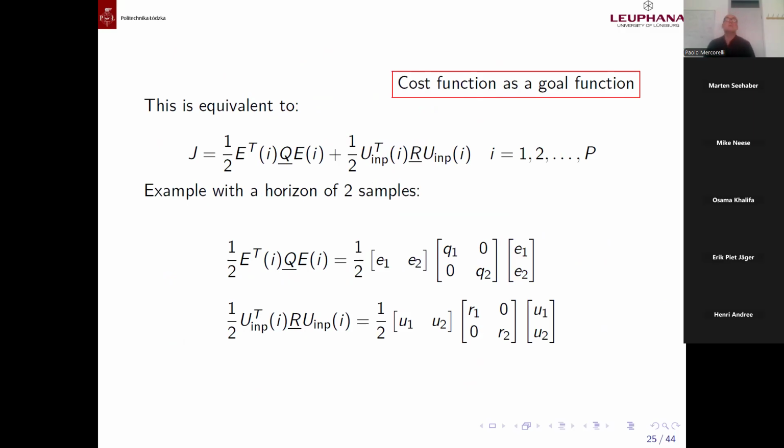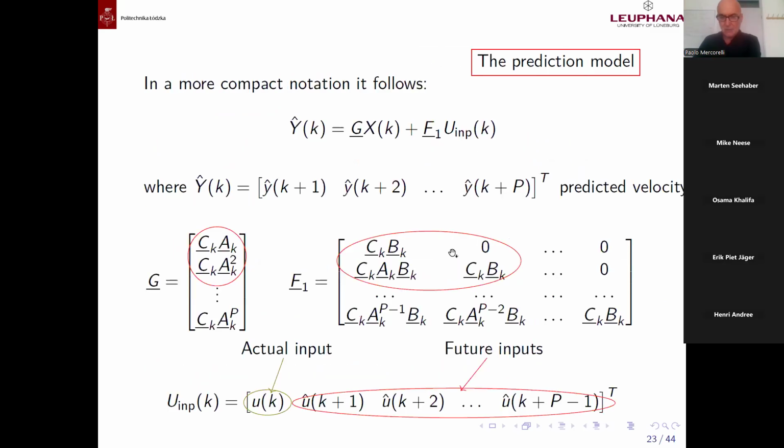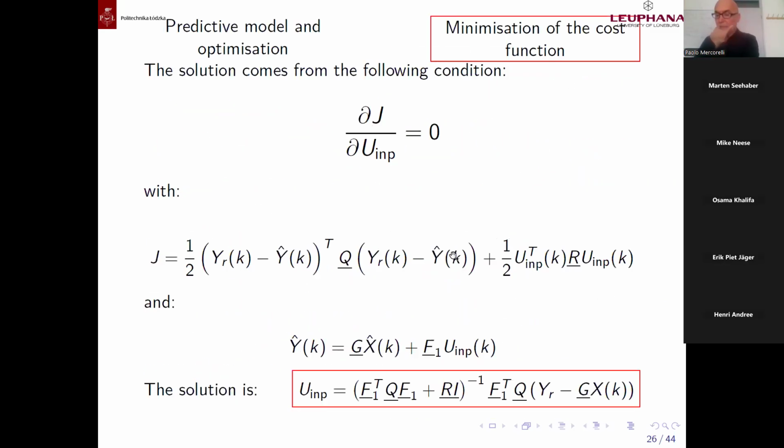But it could happen that I have just one row, because in any case the control horizon could also be less than the predictive one. What I cannot do, because we cannot find the solution, is have two steps in the control horizon and just one in the predictive horizon. We can probably see this more easily from the calculated solutions, because these two dimensions are not compatible.